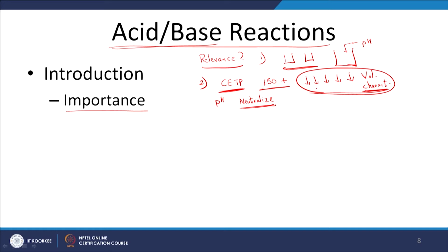So I need to look at the relevant aspects like alkalinity, certainly, and acidity, which you can understand in the context of alkalinity itself, so I will not go further here. So you need to look at alkalinity and acidity and so on, and then look at the amount of acid or base that needs to be put in to be able to neutralize your particular wastewater. So that's one particular example there.